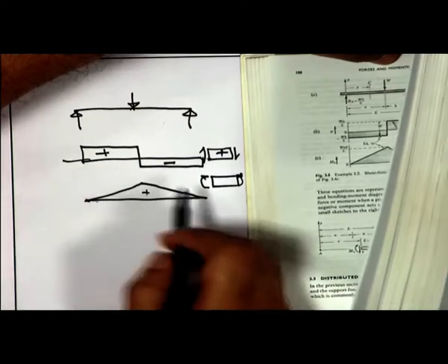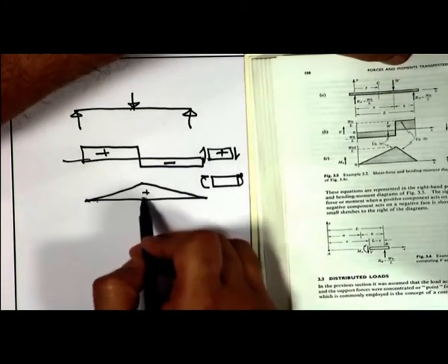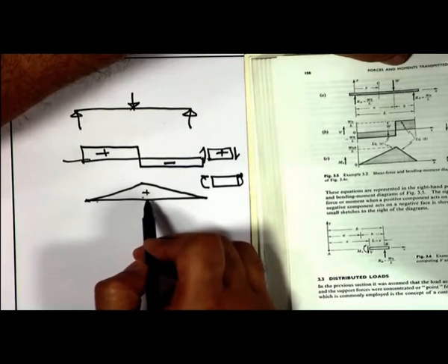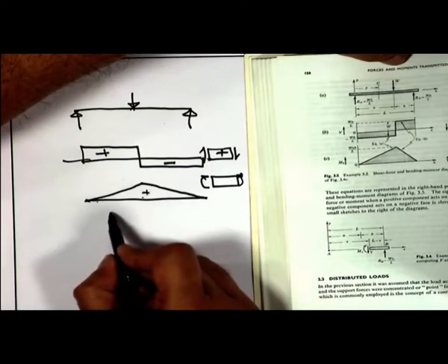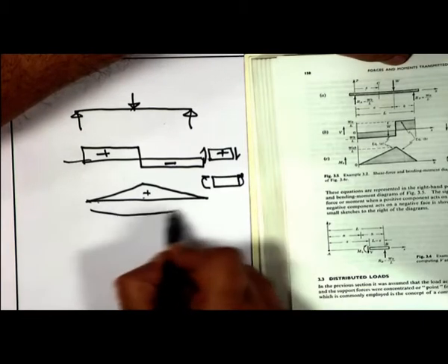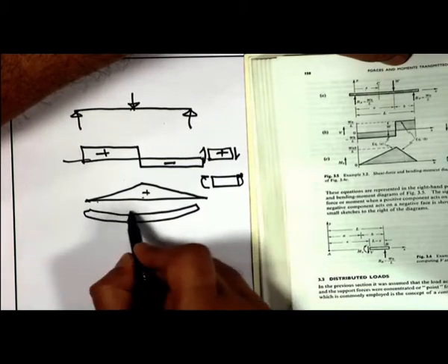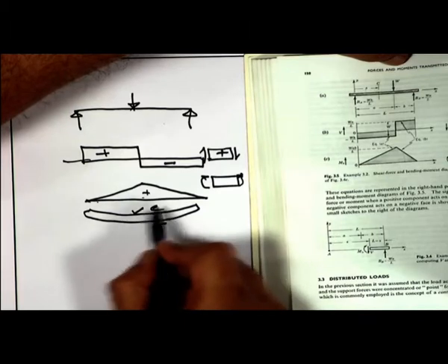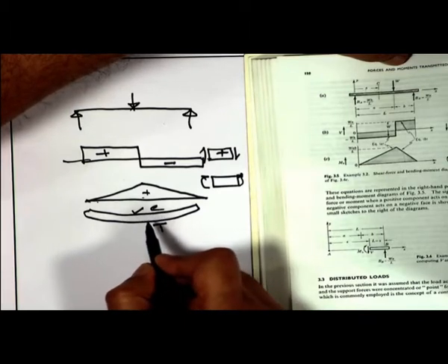Now, I am not putting the values. One thing is in which direction I will plot the bending moment; that also differs from book to book. This book and most books draw the bending moment diagram on the compression side of the beam. It is absolutely arbitrary.